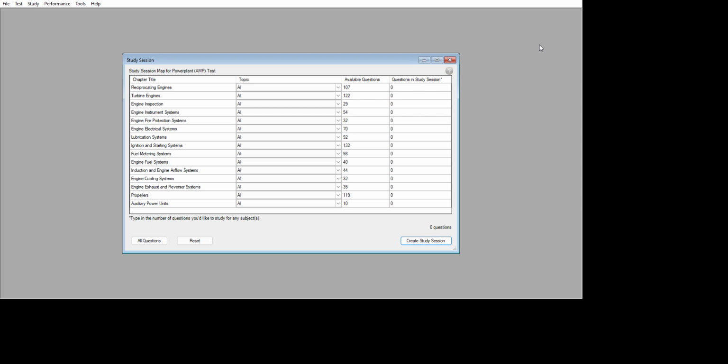An aircraft engine equipped with a pressure type carburetor is started with the primer while the mixture control is positioned in idle cutoff. Inspection of a pneumatic starter by a maintenance technician usually includes checking the oil level and magnetic drain plug condition.